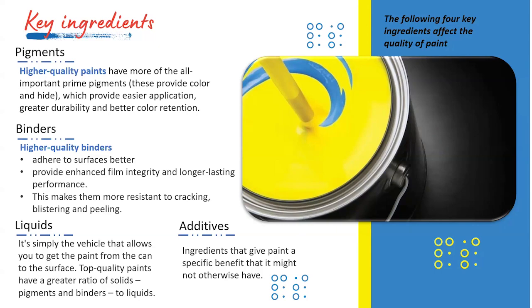Can primers also provide the same properties of a waterproofing membrane for concrete surfaces? Short answer, no. I get brought in on a lot of jobs, like the catwalks, the horizontal surfaces for balconies. While we have waterproofing products, it's best that we address that with a waterproofing membrane.